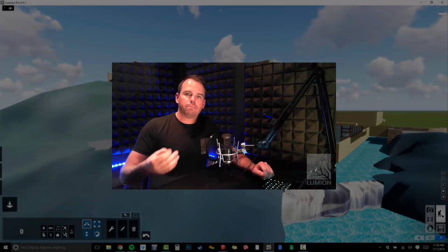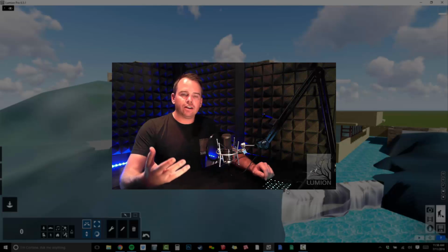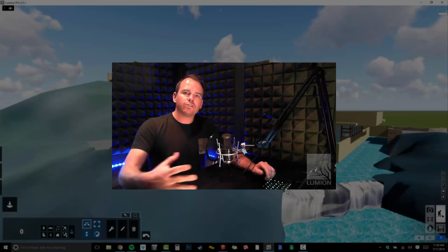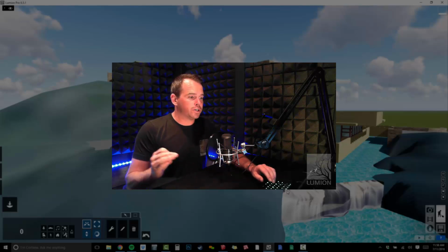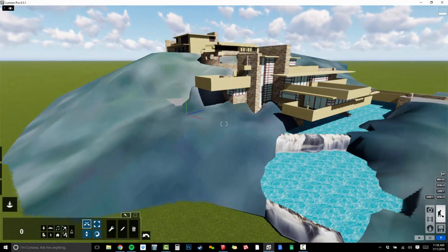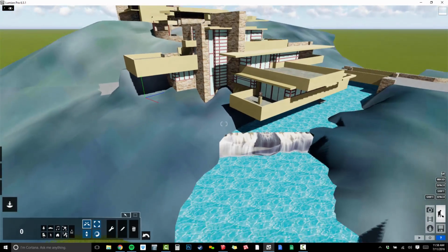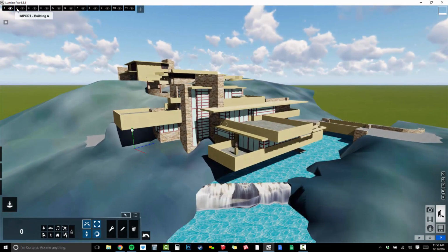So that's why it's important to pay attention to your axes in SketchUp and make sure that when you're saving these models out and breaking them up, that you're working with the exact same origin point. All right, so this one's looking pretty good. The last thing we could do is import our proposed condition.